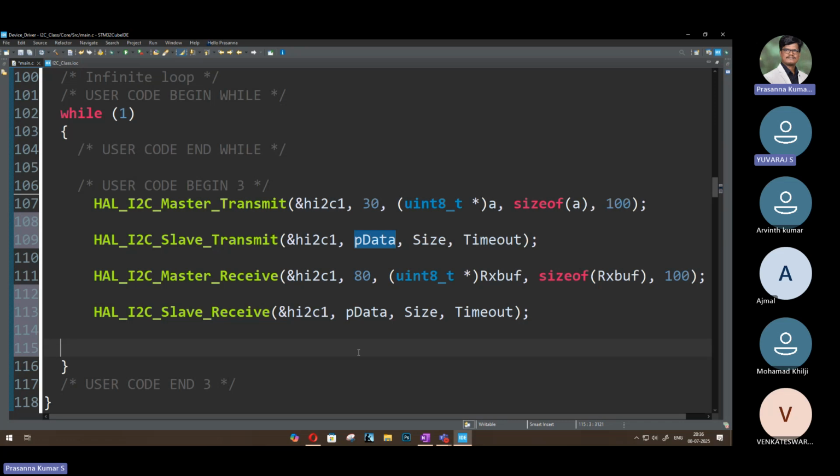Okay. That is what serial communication is, right? We are transferring it bit by bit. As per the frame format of both I2C and UART, you will be transferring or packing 8 bits of data with the start bit and stop bit. Even if you have 32 bits of data, that 32 bits will be segmented into 4 bytes of 8 bits and packed with start bit and stop bit.